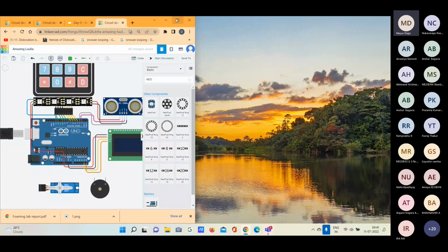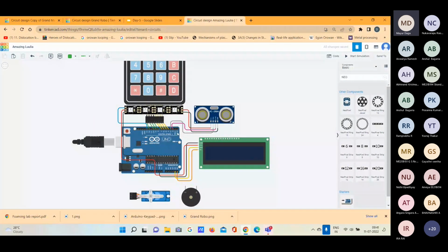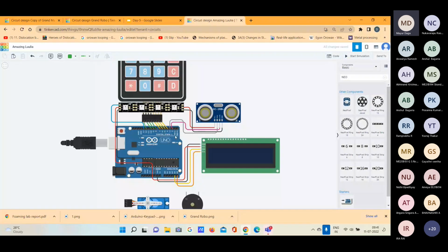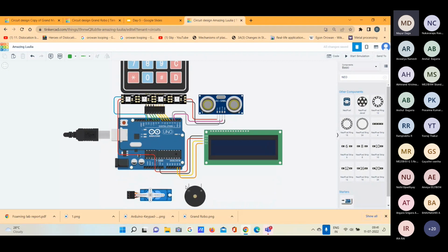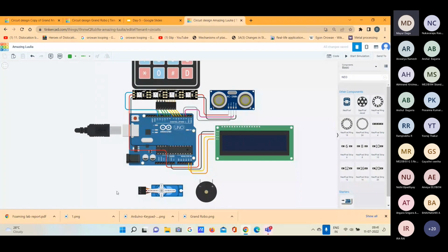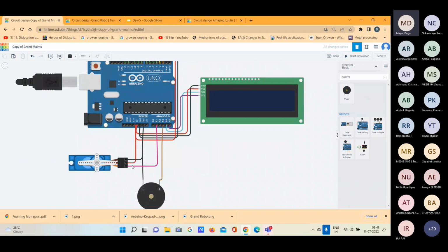Yeah. So now we are almost over with these digital pins. These RX and TX pins we won't recommend you to use. And now we'll use the analog pins of Arduino as the digital pins. Okay. So let's see once. Yeah. So we'll connect the signal pin of the servo to pin A1.